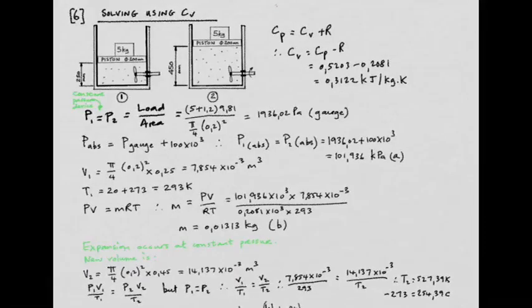Now, if this piston is to rise from 250 to 450 millimeters from the bottom, it's clear that there's got to be an increase in volume. Let's see what the second volume has to be. Well, it is the same diameter, 0.2 meters, times the new length of the cylinder that we are dealing with at 0.45. So we have 14.137 times 10 to the minus 3 cubic meters.